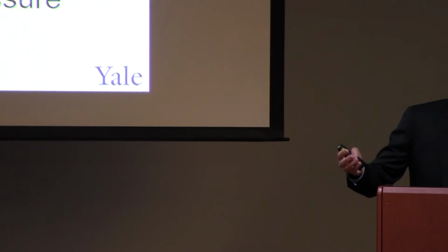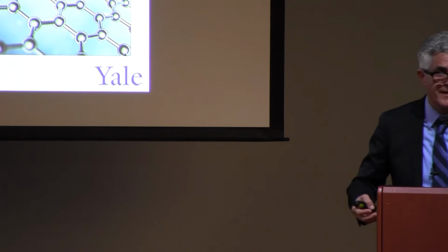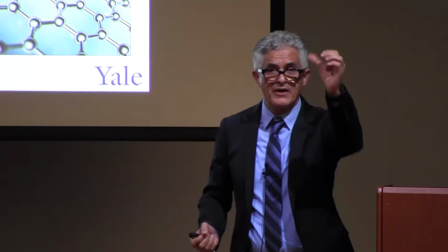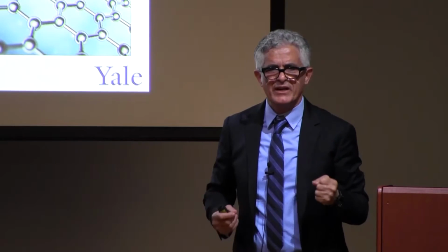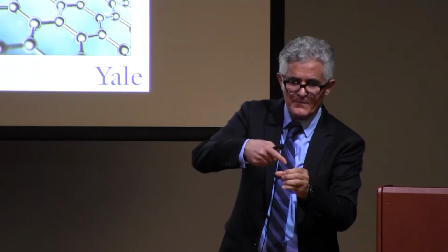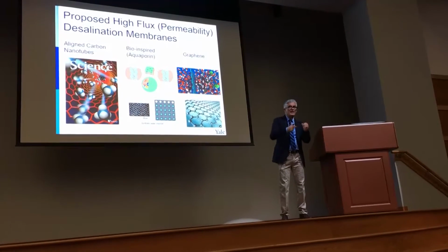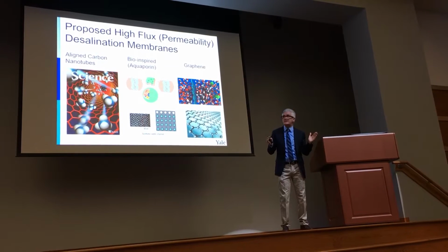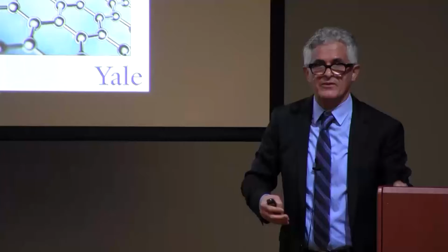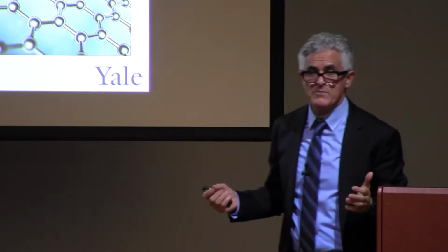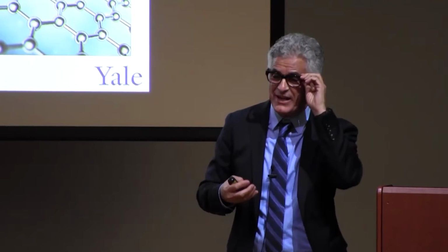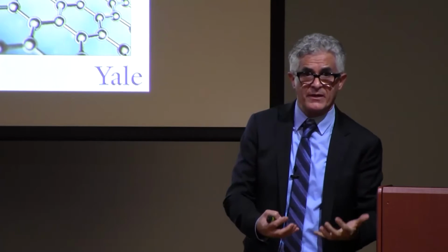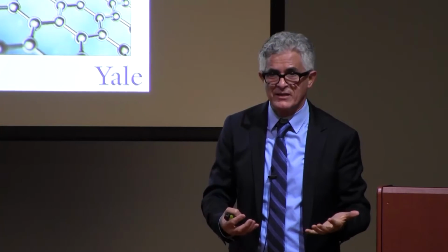There were plenty of studies, and they resulted in top papers in Science, Nature, and so on. They thought about carbon nanotubes, and found that the water flow there is very high because the tubes are hydrophobic and smooth, and the water goes through in a single file, where the no-slip boundary condition doesn't hold. They promised that this may revolutionize desalination. Aquaporin membranes, the protein channel, which I will talk about later in the talk, can transfer water at a high rate, and people thought that if you incorporate them into membranes, you can increase the permeability and save energy.